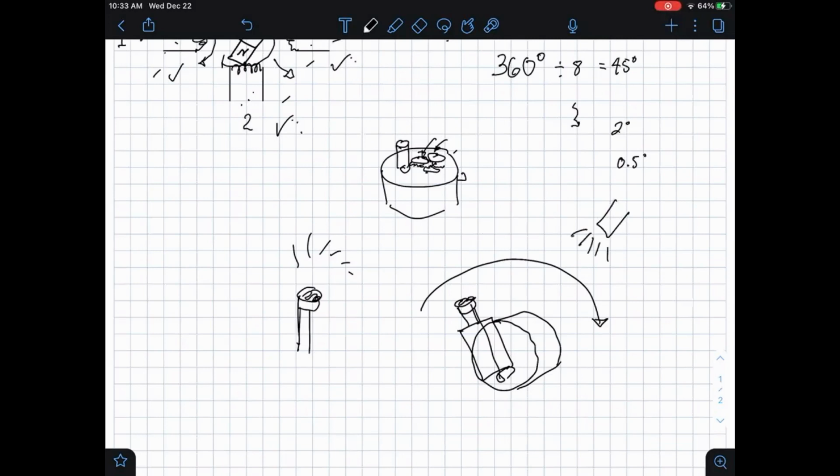What the electronic sunflower will do is sample here: rotate first, look at the voltage value. Then move it another step. It's up to you what delta angle to use, since it samples the brightness here and compares it to the brightness measured in this position. Then you will read and read in all different positions, and compare where the brightest is. And then you will finally turn the electronic sunflower to where it is